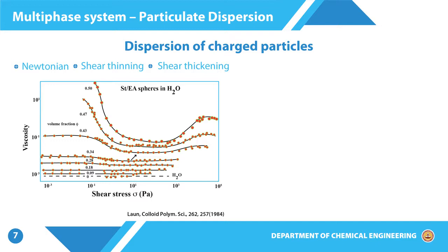And so, shear thinning is again observed because in most such cases it would be natural to expect the particulates to break up, the clusters to break up, and therefore, viscosity to go down significantly. And again one observes a response in which over a significant range of stress or strain rates the viscosity remains constant, but then beyond a certain stress or strain rate, again a viscosity increase is observed.